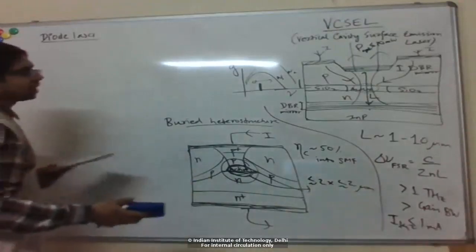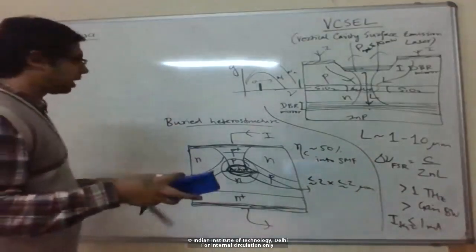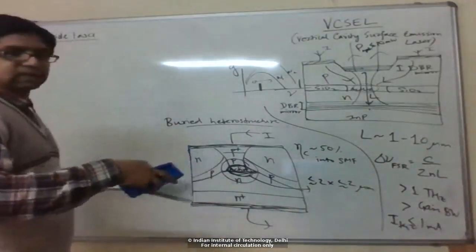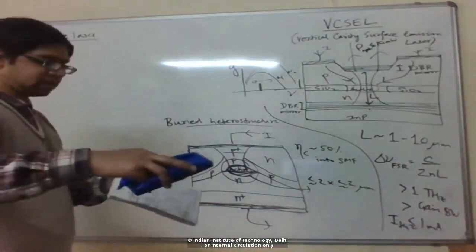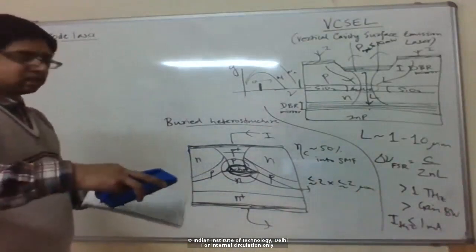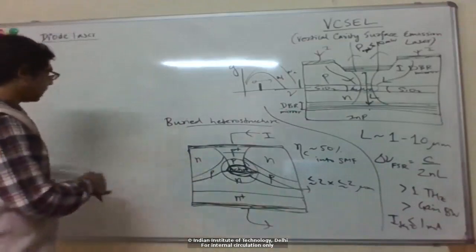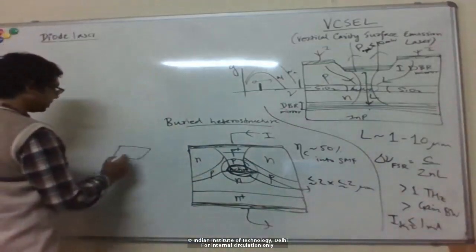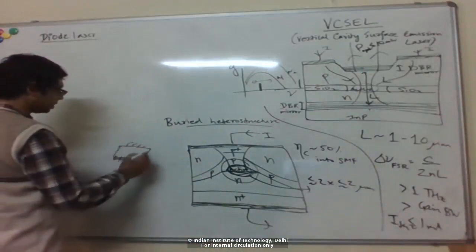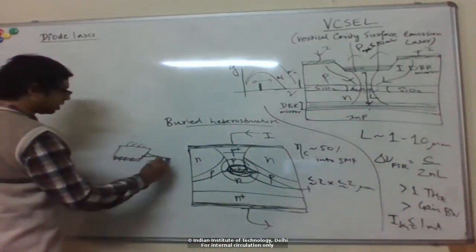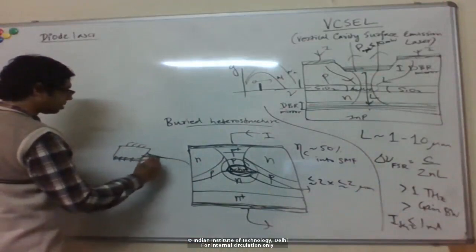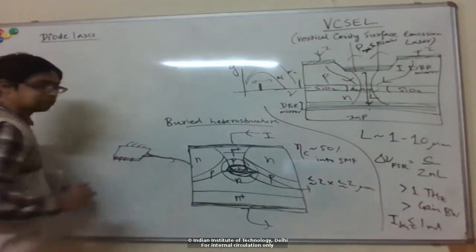These lasers are typically grown on a small chip, and then they can be packaged along with the optics, and the fiber is what is known as pigtailed, or directly attached to the device. So basically what you get is a packaged device, typically what is known as a butterfly package, and the fiber is already attached to it, and the light comes out directly into my fiber.